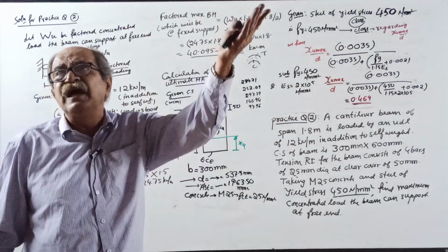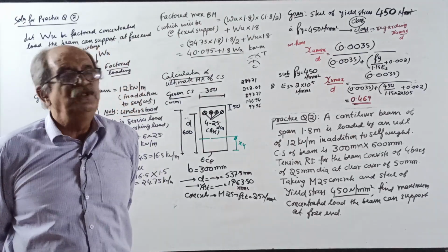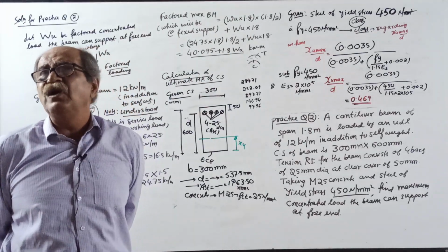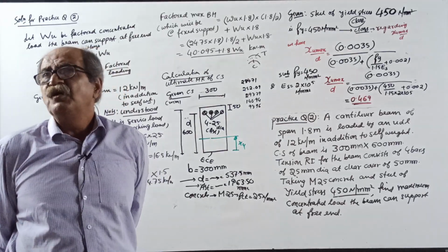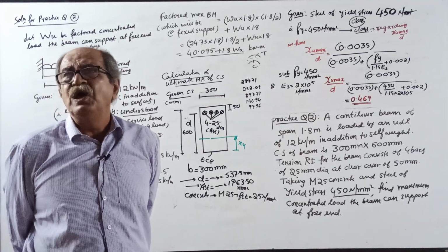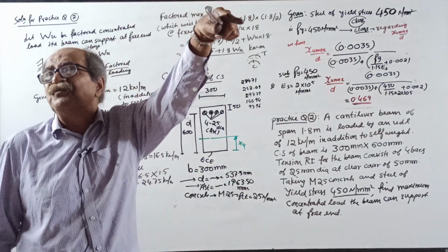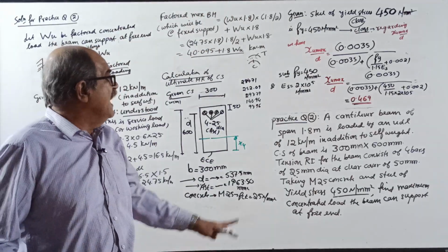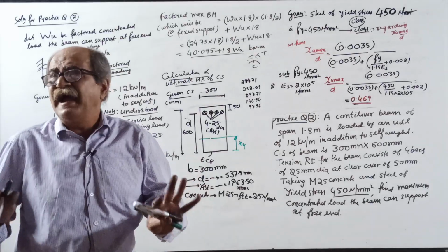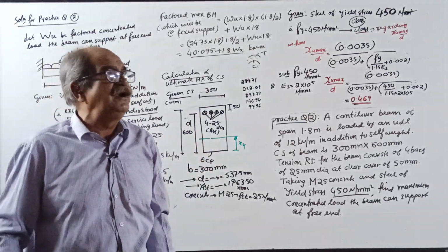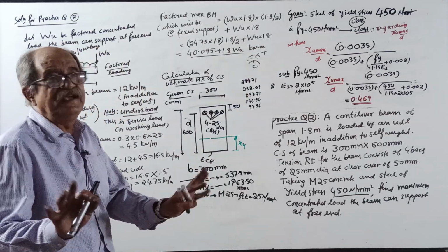In the design field, I do it some other way. When I do practical design, I never factor the loading. Always in the software we give working load, but during the design we factor. But for analysis, usually this is better, from an academic or understanding point of view. Okay, don't worry about those things.